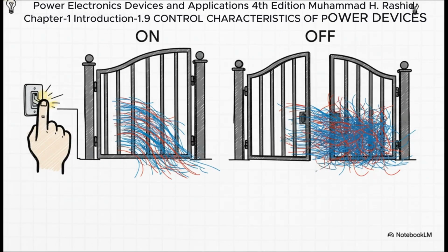And that brings us to our 4th philosophy, which really is the modern approach you'll see everywhere. This is the world of MOSFETs and IGBTs. The big breakthrough here? We're not controlling with current anymore. We're controlling with voltage. You apply a positive voltage to the gate, it turns on. You remove that voltage, bring it back to 0, it turns off. And here's the beautiful part. These devices have an incredibly high input impedance. That's a fancy way of saying it takes practically 0 current to control them. This is what makes them so efficient and allows for the mind-bogglingly fast switching speeds we rely on today.